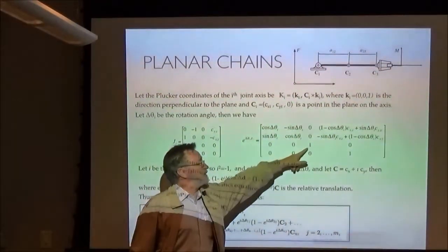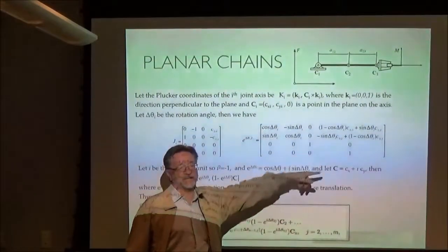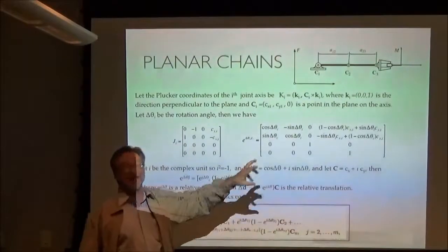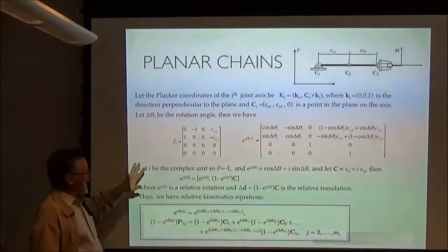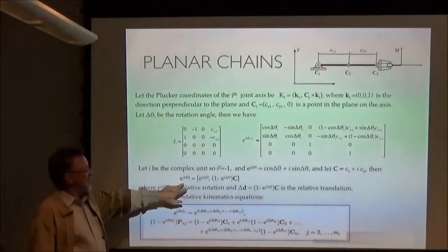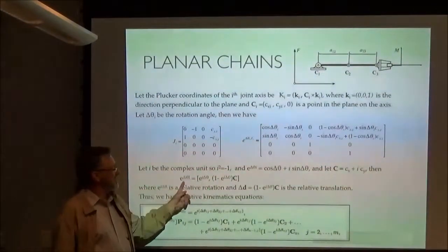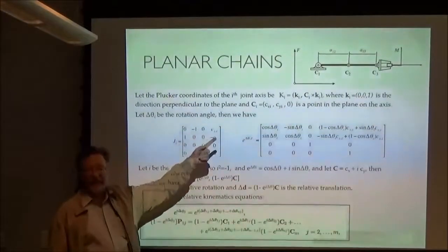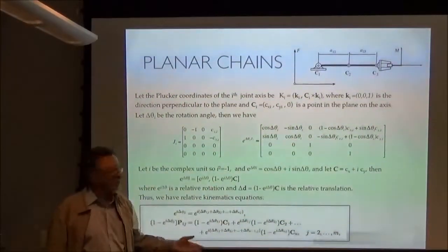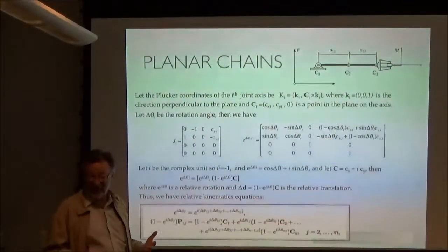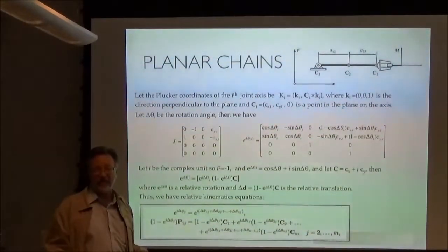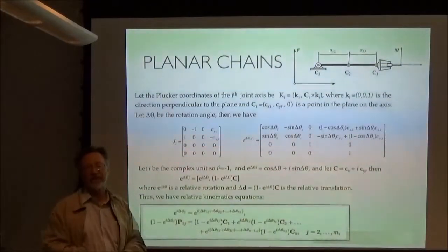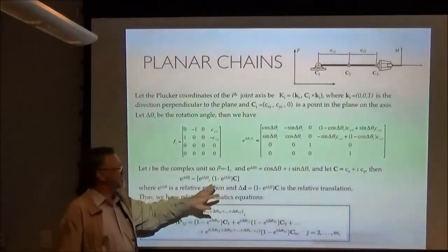It's a rotation matrix. The z-axis and the w-axis don't move. That represents the translation associated with it. And it's not uncommon. You'll wind up seeing a matrix that looks like this. So this is the product of exponentials form of the planar robot. It turns out it has a form that's somewhat familiar. Any of you who've been involved or studied with Art Erdman and worked with his standard form equations, some of this will look familiar to you.